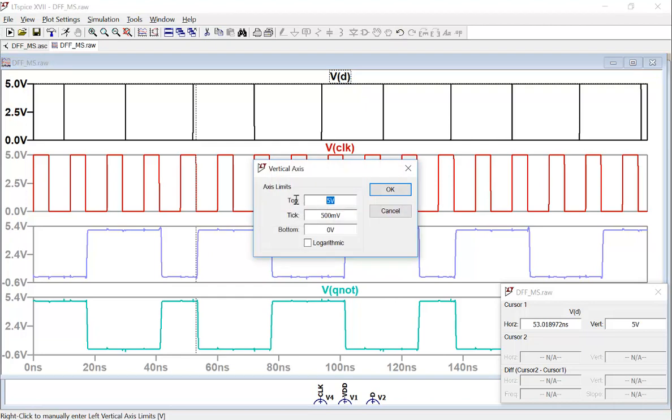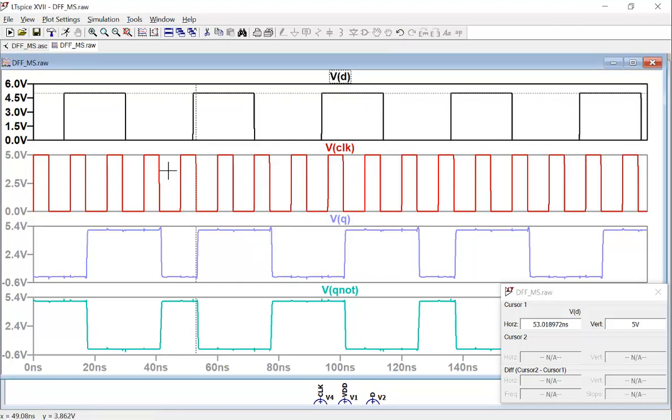So let's see, okay. I have a falling edge and 0. Now let's pick up a thing like, for example, here, right? At the falling edge, it sends a 0 to Q, and still at the logic 0 for clock. But now D changes, right? So D has a rising edge and goes to 1 when the clock is 0.